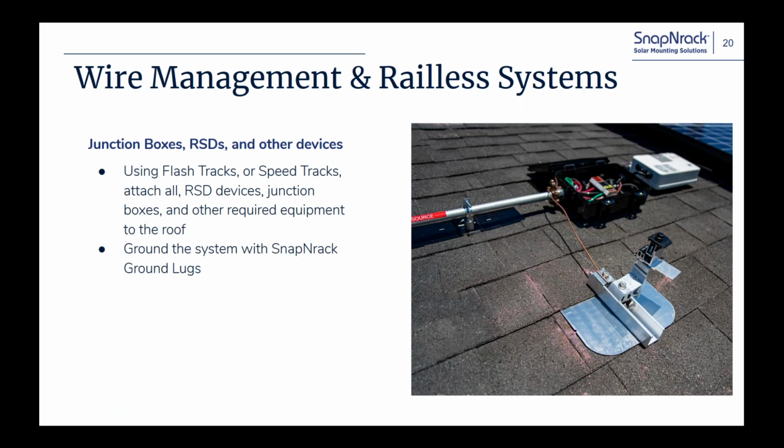So here's an example of one full array. As you install it, the top corner module is the last module that goes down, and that's where you run your last little bit of copper right to the J-box to finish that grounding of the array.